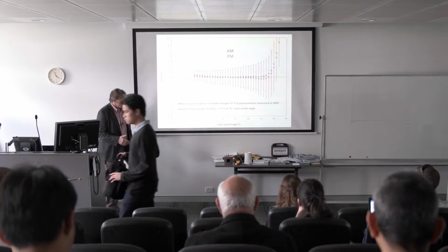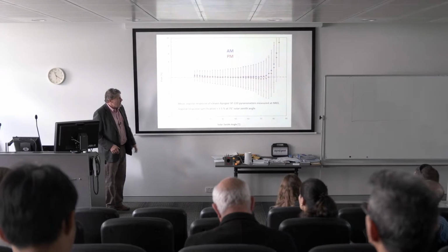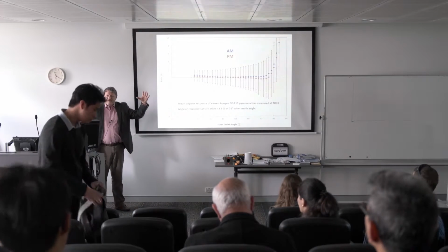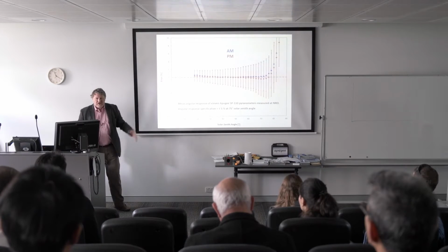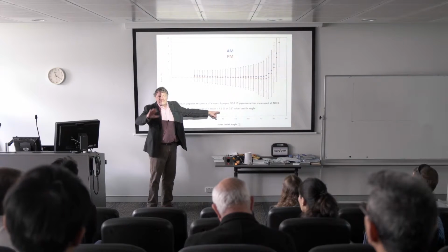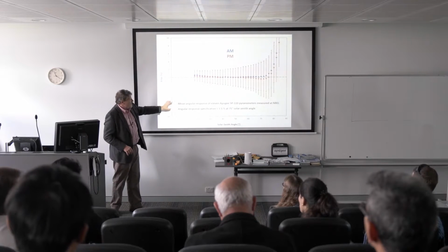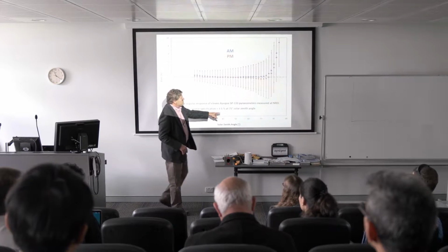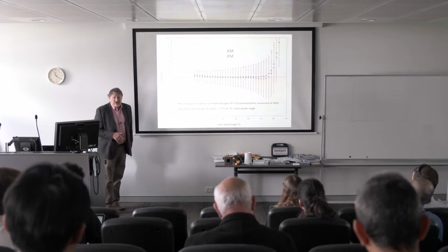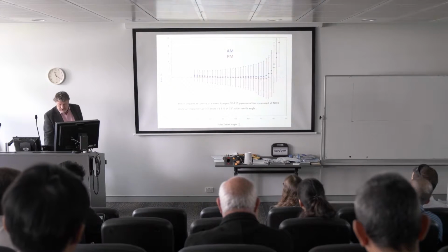And this is an example of how companies write specifications too. How accurate are they out there? You can't just test one sensor. You've got to take your entire pool of sensors with replicates, and you want to make sure your specification matches all your instruments, not just your best sensors. So we specify 5% at 75 degrees, and this is 2 times the standard deviation, which is 96% of the tested sensors.